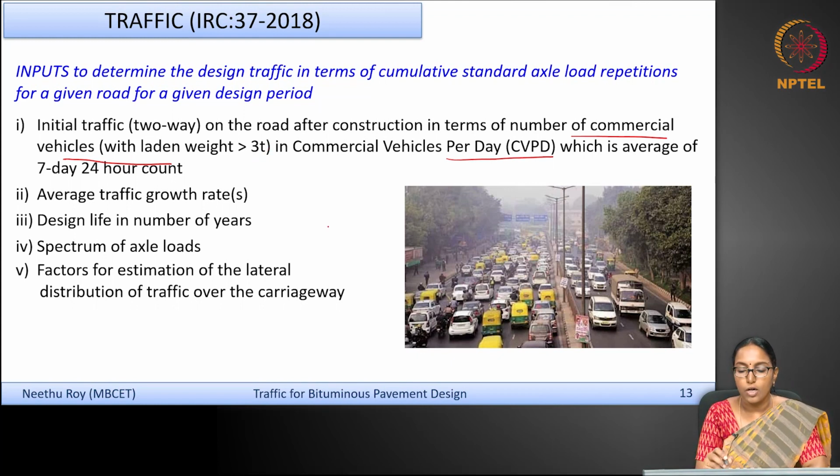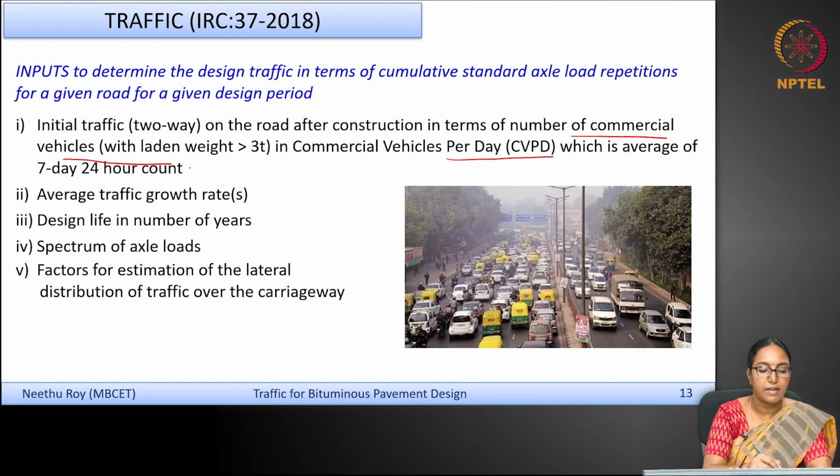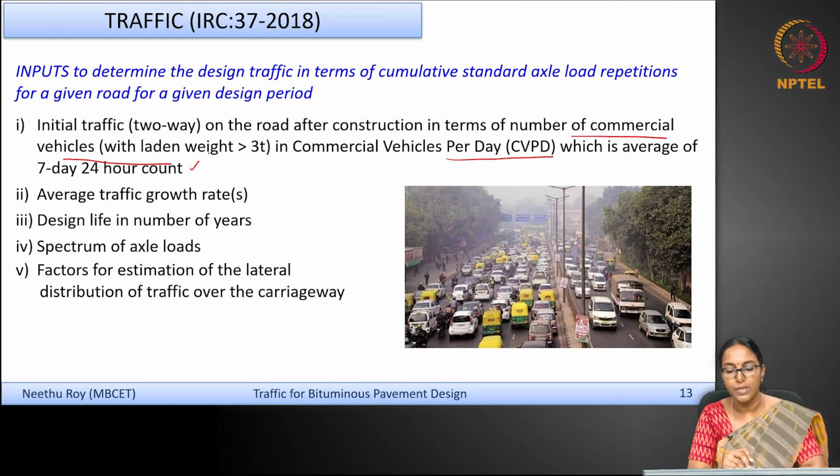In order to get this commercial vehicles per day, you have to take the average of a 7-day 24-hour count. So this number of commercial vehicles per day should be the count at the beginning of the functioning of the new structure or the new pavement.